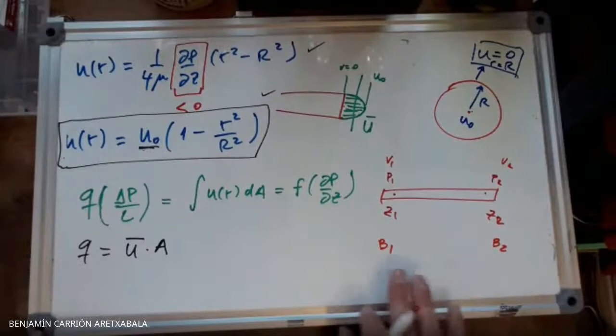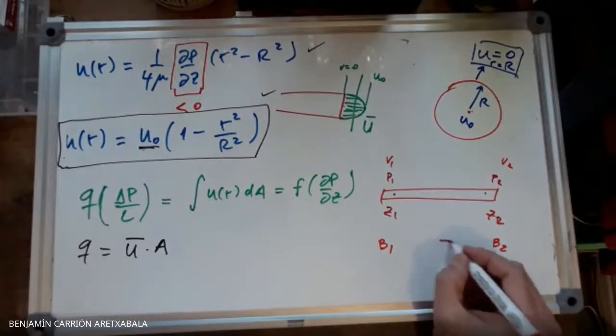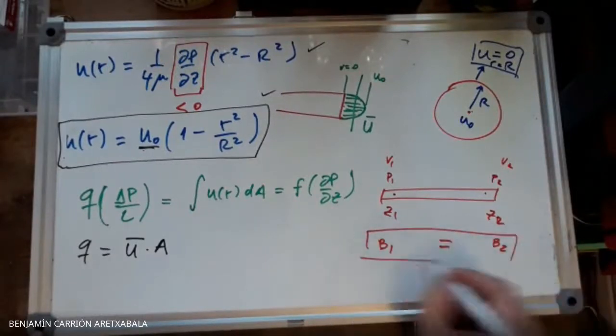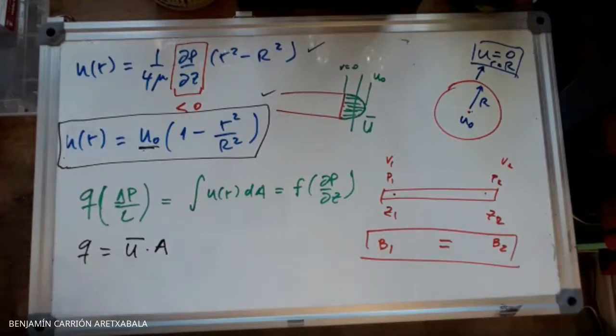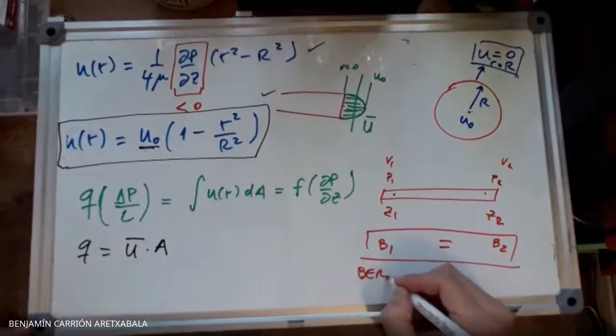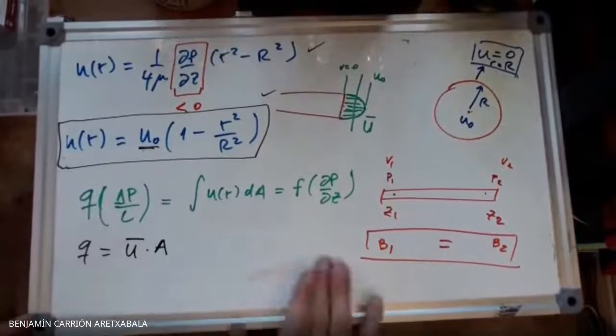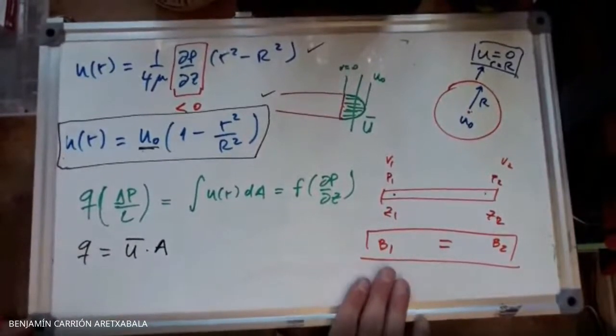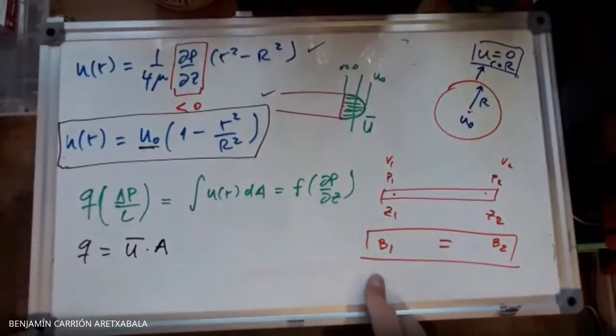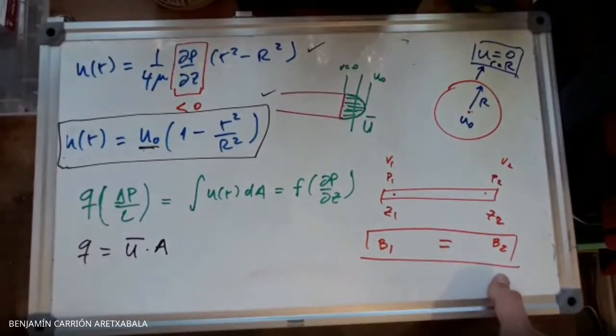But when did we do this? When could we say that the Boussinesq was conserved? What do you mean in English, Matthias? B1. I'm sorry, the Bernoulli. Yeah, sorry, this is the Bernoulli. Boussinesq is another famous name in hydraulics. I just got them confused. So the Bernoulli here has to be the same as the Bernoulli here, right?